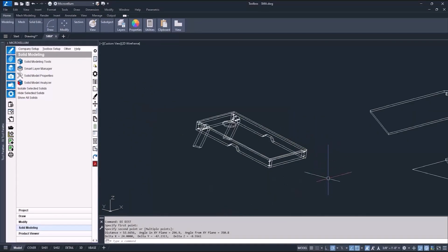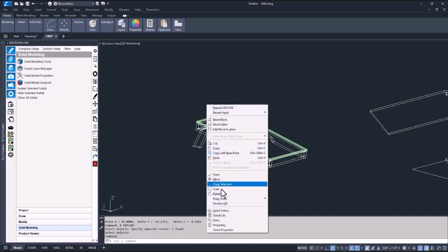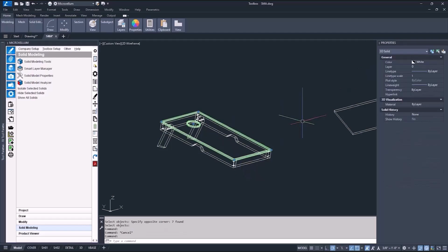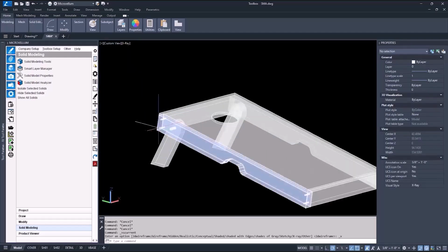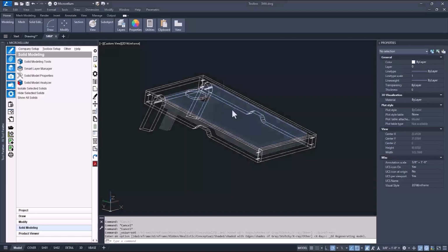That's close enough. If I was really wanting to get these parts cut, I would go through and make sure each of the 3 solids are matching the correct thickness and all the sizes were correct too. But I wouldn't even really be able to do that at this point with the block in its current state. That's because it's just a block reference. So I'll need to explode it so those parts are actually 3D solids. Also, these holes, I would want to make sure match the diameter of a drill bit that's in the tool file. Otherwise, they're going to get ignored.